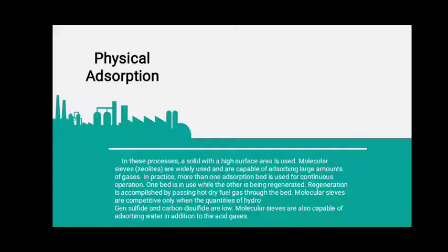Molecular sieves are competitive only when the quantities of hydrogen sulfide and carbon disulfide are low. Molecular sieves are also capable of adsorbing water in addition to the acid gases. So in physical adsorption, a solid like zeolite adsorbs the gas from the natural gas.